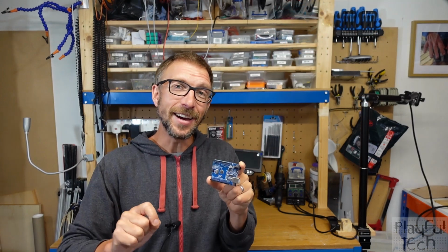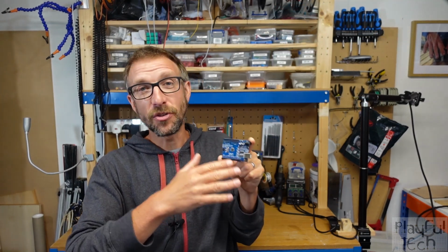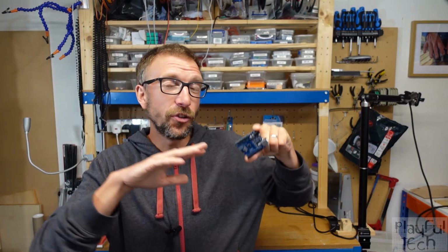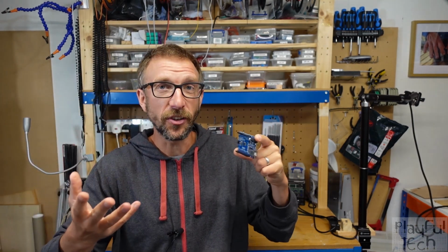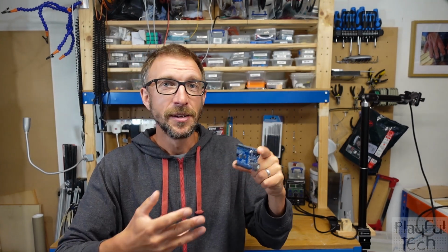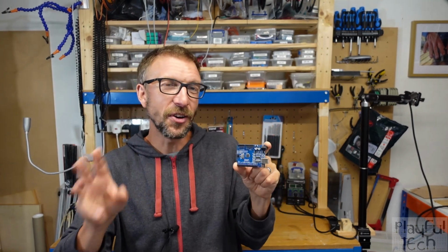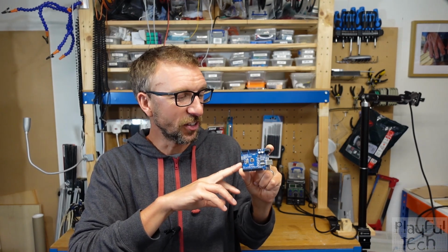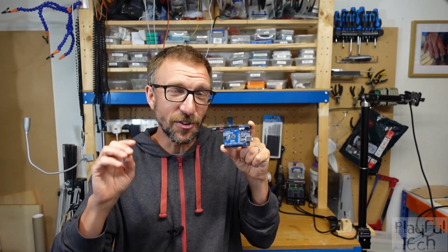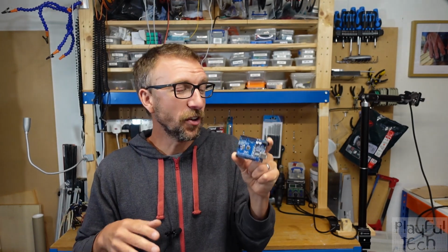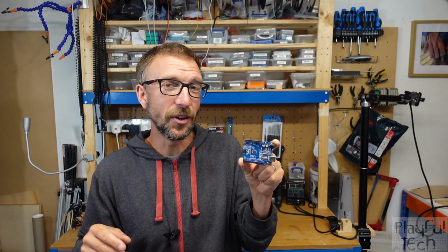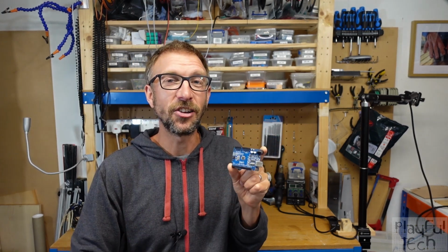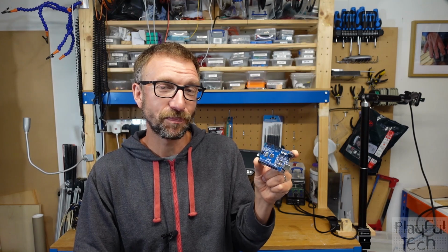Now the problem here is that in every case when you convert a signal, there's the potential to introduce noise or to affect the signal quality in some way, to slow it down. And so even though logic level converters can potentially correct the problem of having the incorrect voltage, they may actually introduce other errors as well. There's lots of different sorts of logic level converters, so it's very important to select one that's appropriate for the application you're trying to use it for.